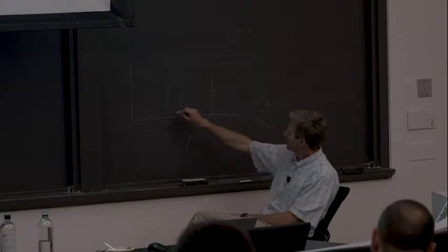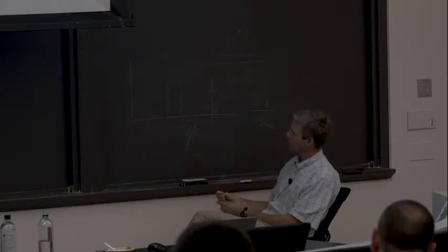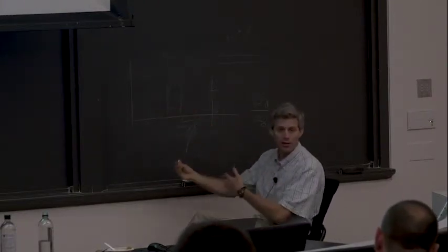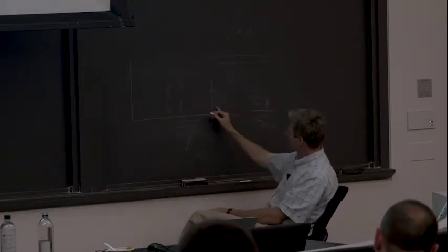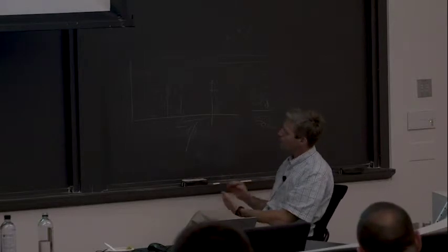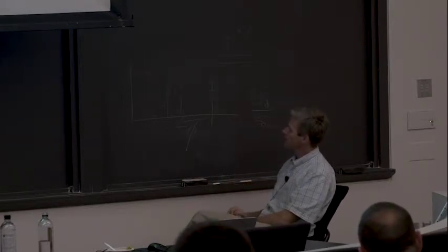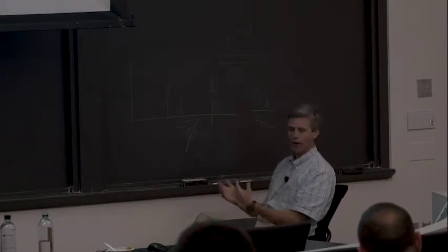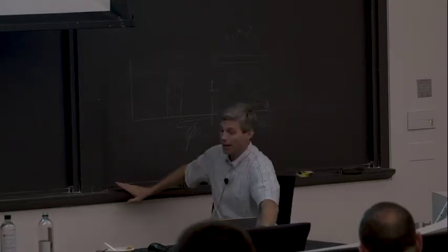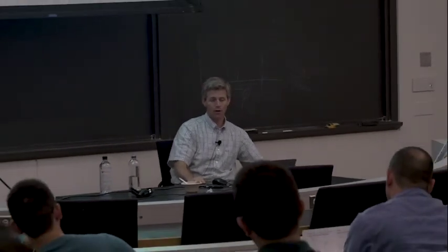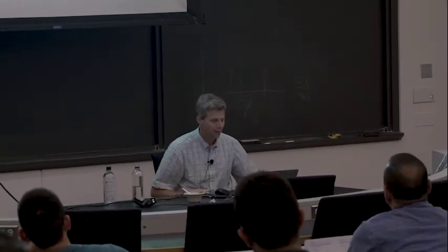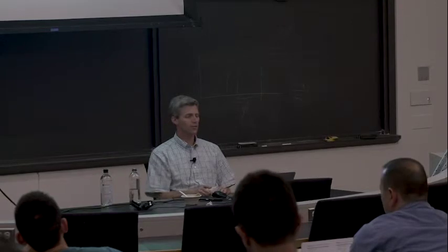But because that and that are presumably correlated, if I now double the velocity and repeat the experiment, these things will move, but I still get the same idea. Because these are correlated, that's probably what's driving the success of a lot of the classical scalings you'll see in the literature. But I want to emphasize that if you think about what's really fundamentally happening as flames are blowing off, I don't think a lot of these blow-off scaling approaches are really telling you what's happening. They're just telling you when you're starting to get extinction.